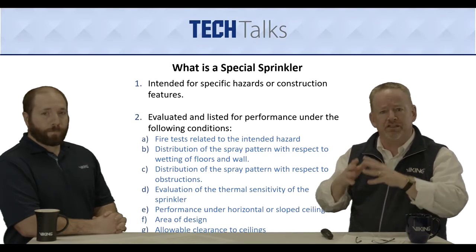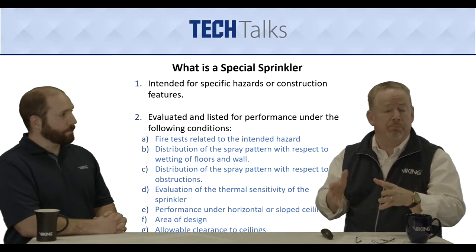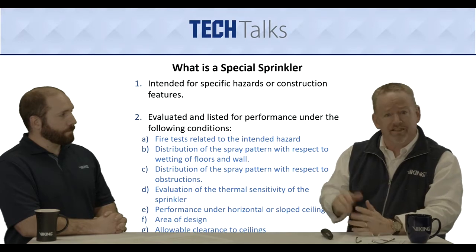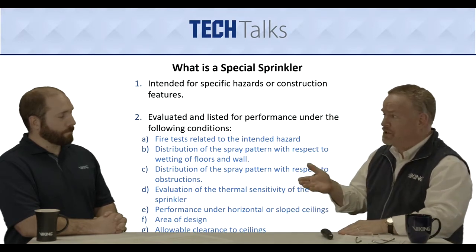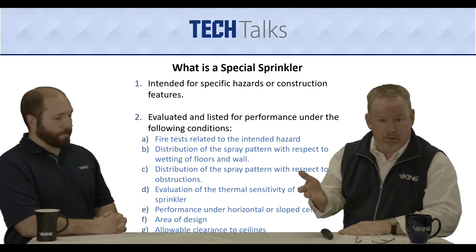That's the first definition of a special sprinkler by NFPA 13's standards. The second is that not only is it for a specific hazard or construction feature, but it has to develop its own test protocols as well.